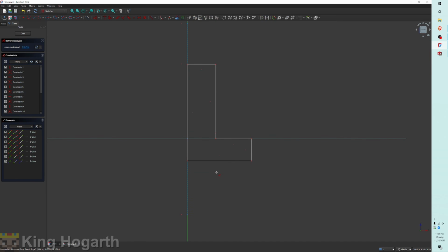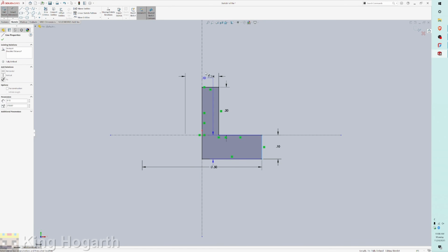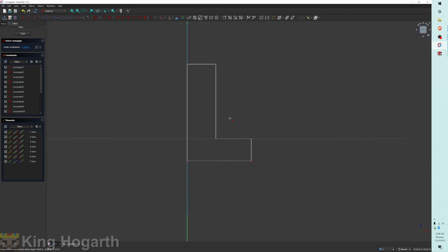In SolidWorks, if you don't know, if we click this line to this line, we can actually go to the opposite side of the sketch, and we'll create a dimension as if it was revolved. It would be a 1/4 inch here or 1/2 inch here. So it does not appear that FreeCAD has that ability. We're going to continue on dimensioning the rest of it.